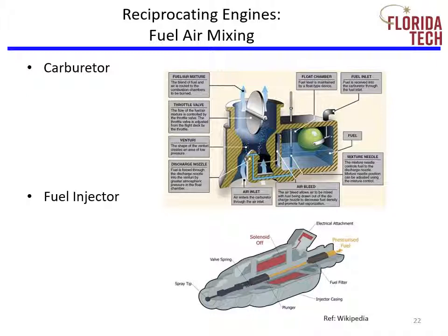The fuel pump pumps fuel from the fuel tanks into the fuel control unit. Then, the fuel control unit regulates the specific amount of fuel needed based on the mixture and throttle settings. The fuel then gets sent to the fuel manifold valve, where it is dispersed and heads to the nozzles of each cylinder. This time the fuel does not mix with the air until immediately before entering the combustion chamber.